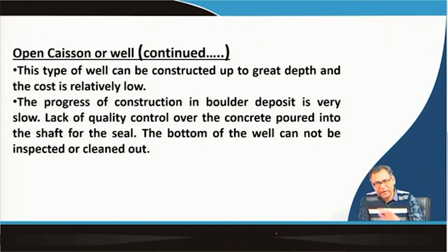Once it is sealed and filled by the sand, then the top plug or the top portion is concreted, and then it is sealed. So, this is the total construction process for the open caisson. It has some advantages and limitations also.